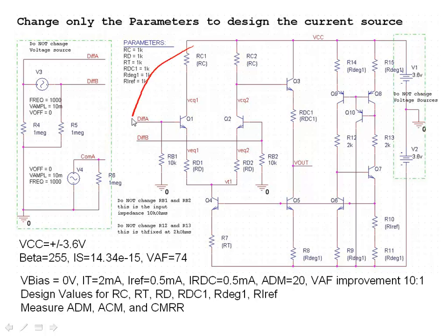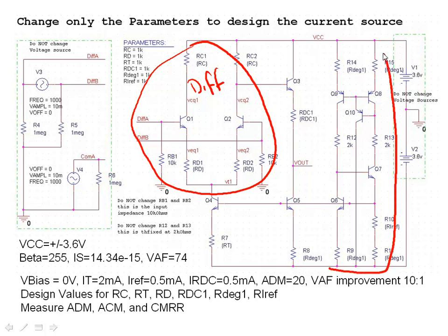This part of the circuit is a straightforward differential amplifier, so that's the diff. I'm going to postpone actually working on the diff. First off, I'm going to work on this part over here, and this part is a reference cell for a current source. So this is effectively the reference side of a current source. Okay, let's just have a little note about one or two specifications. A couple of things on my circuit diagrams as well which are quite useful.